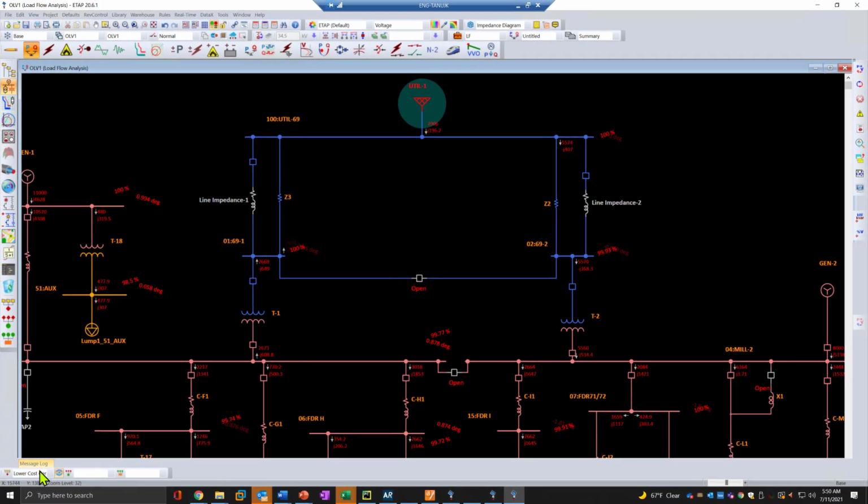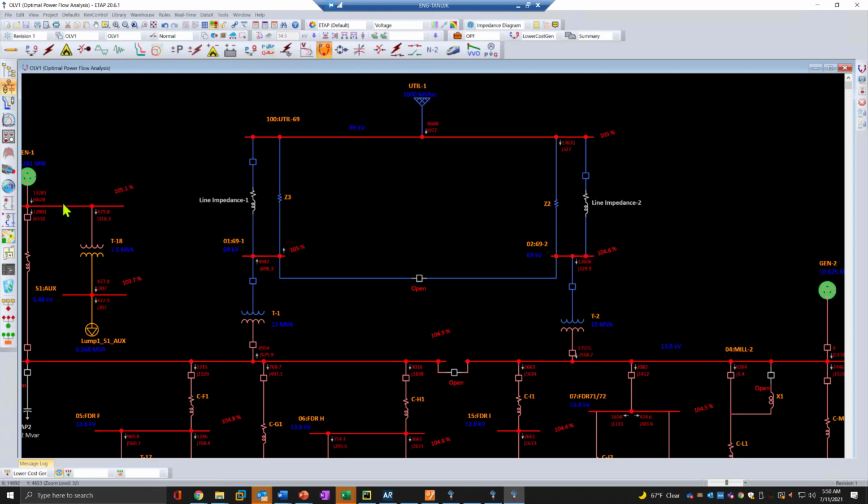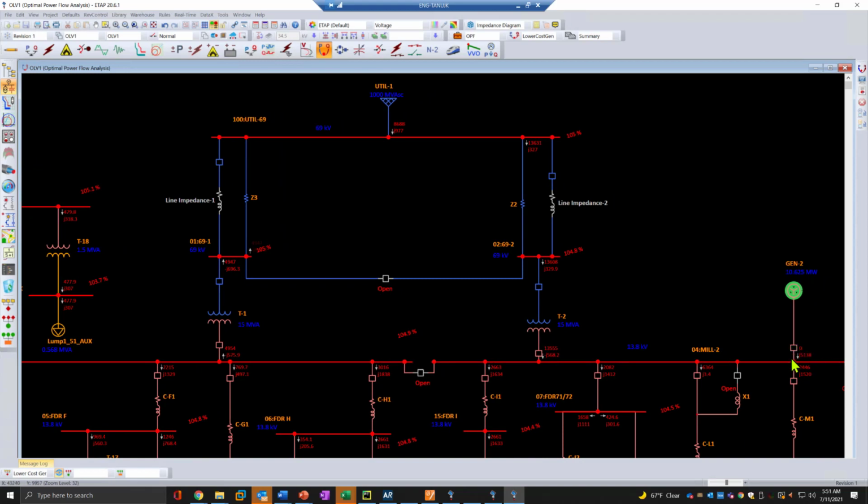So the first scenario that I've already created in the interest of time is when we want to minimize the cost on the system such that the generator 1 is actually the cheapest source, while generator 2 is actually not the cheapest source. So here we can see OPF rebalancing such that we are using generator 2 purely for its reactive power and not the real power output.